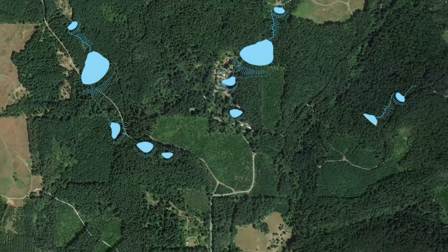A stage of equipment mobilization, potentially even prior to mobilizing large equipment for pond construction, is to have a machine that can dig a nice and deep test pit. The test pit is very important because it helps you evaluate what type of soil conditions you have for pond construction. The day that you do the test pit is a day to both do field analysis of your soil and also collect soil if you wanted to send it off to a lab to have further samples.